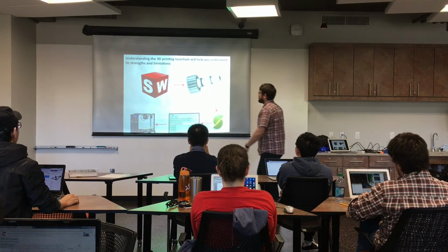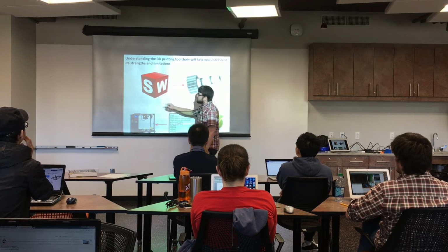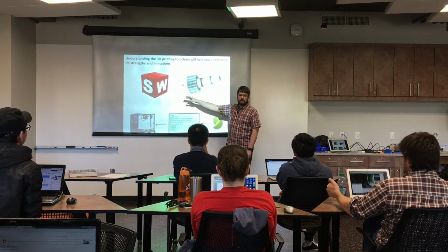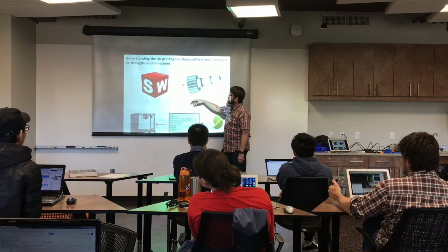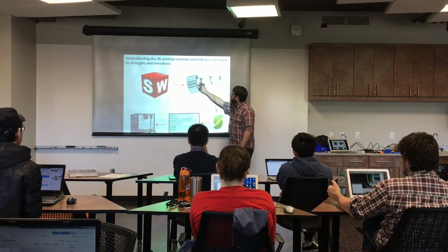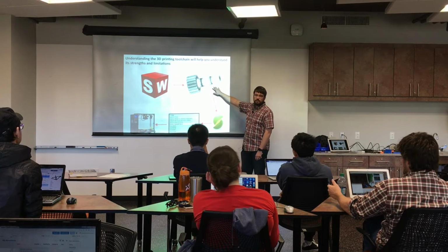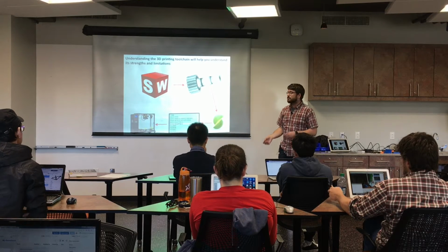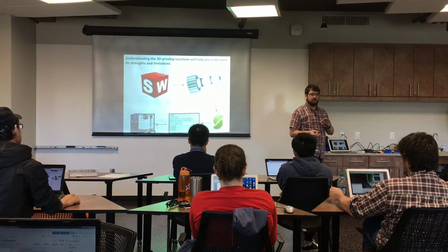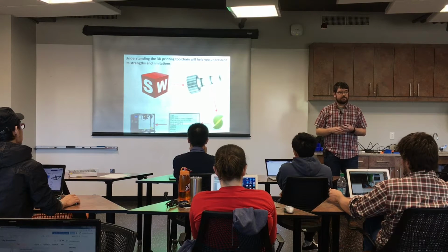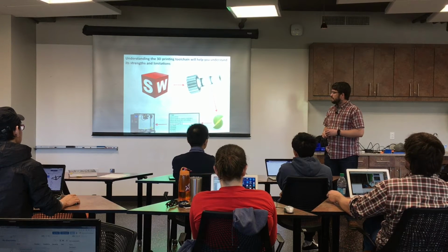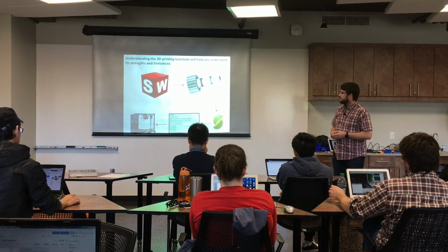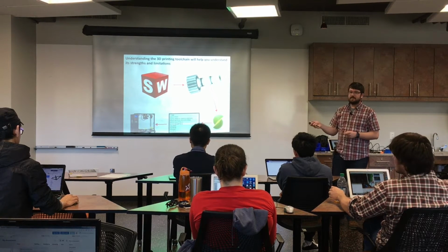So when you send your file, I would say you'll probably be best off sending the library an STL file, because if you send them a Parasolid file or something from your CAD tool, they may not know how to read that. But if you go with an STL file and send that off to a service bureau, they'll take care of the slicing and G-code generation because that is machine specific. Each different machine, you're going to do the G-code a little bit of a different way. It's kind of like when they run the CNC lathes at the shop, they have a post-processor that they run the G-code through for each different machine. Does that make sense? All right.